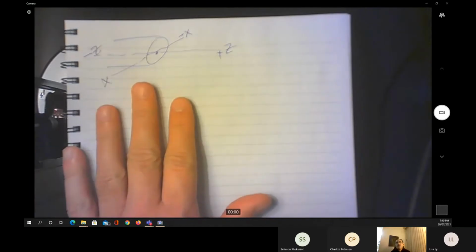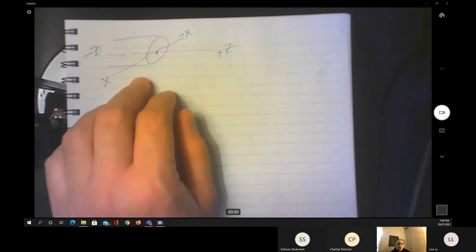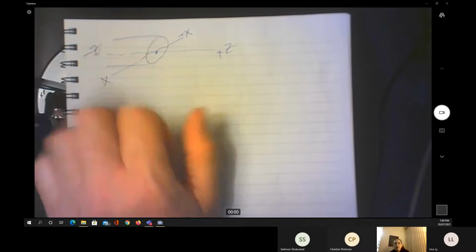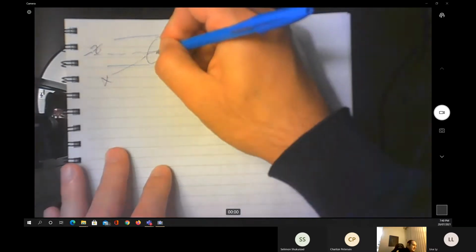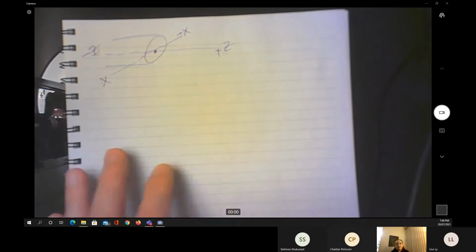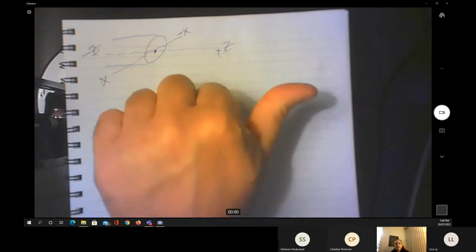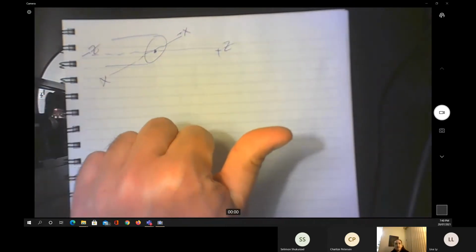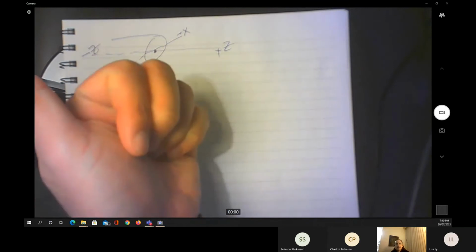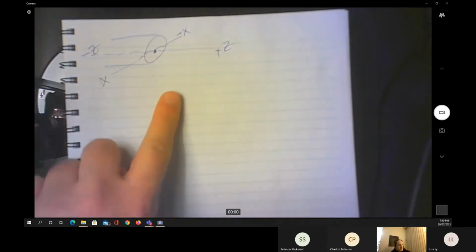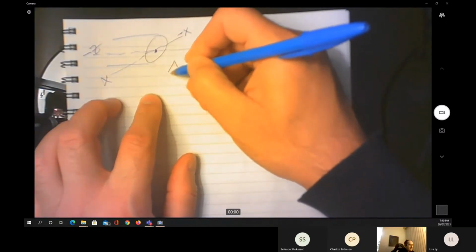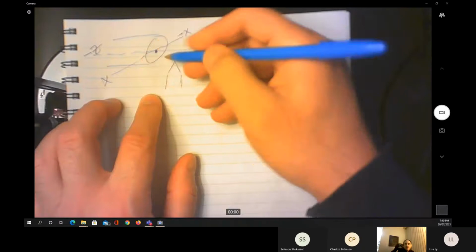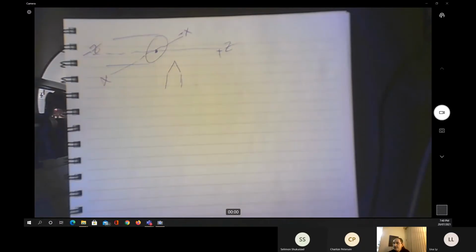So for the turning operation, the datum point usually is going to be on the face of the work part, here, at the center of the face. Again, anything in this direction is going to be positive x, z, negative z, negative x, positive x. So the tool post usually is going to move the cutting tool in this direction to be in contact with the work.